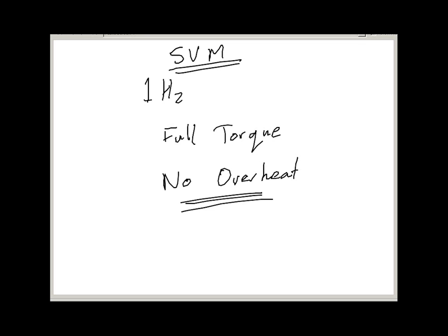It doesn't affect the speed control in any way. The VSD works completely normally. The only thing that you do have to do is that each motor has got its own iron loss or iron constant fingerprint, if you will. And that is an individual thing for each motor. So when you buy this, you generally buy the VSD and the motor as a matched pair. And they come as a matched pair, with the VSD knowing all of the motor's iron loss characteristics.